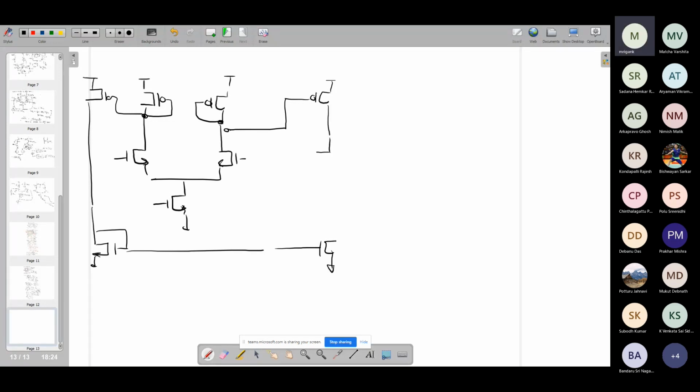At this stage we had basically put a PMOS and an NMOS stack to get the cascode. Now the question may be: how are we going to realize the gate voltages of these two? For that, again, we need to carefully choose the DC bias points of these. We know in terms of swing how it is going to affect, right?